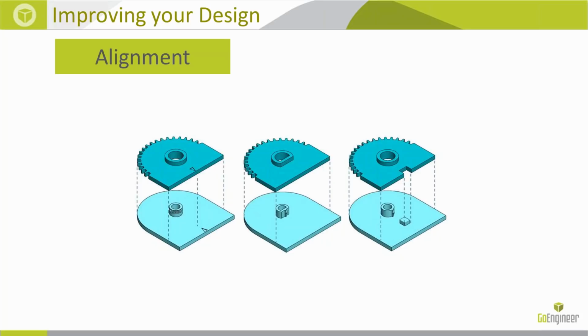And then the third example builds upon the second one, where you have a snap groove that you snap it on. So that's kind of like your vertical or your Z direction feedback. But then you also have another feature to indicate the orientation to keep it from rotating around that boss once it's snapped shut.